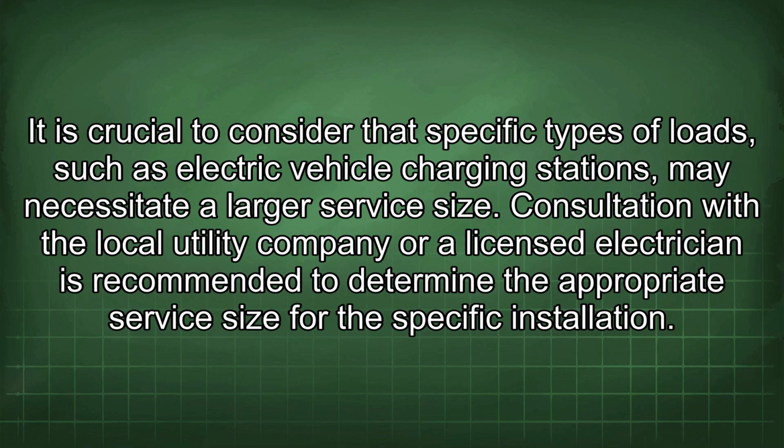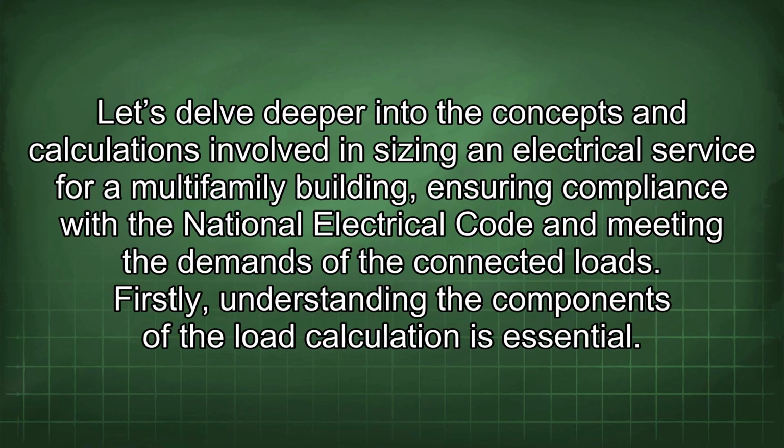It is crucial to consider that specific types of loads, such as electric vehicle charging stations, may necessitate a larger service size. Consultation with the local utility company or a licensed electrician is recommended to determine the appropriate service size for the specific installation. Let's delve deeper into the concepts and calculations involved in sizing an electrical service for a multifamily building, ensuring compliance with the National Electrical Code and meeting the demands of the connected load.